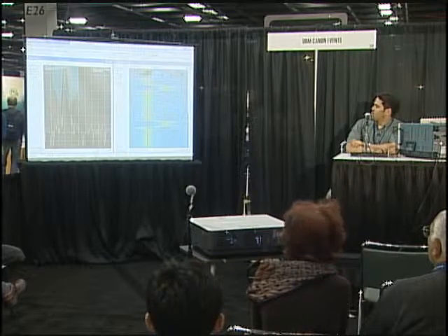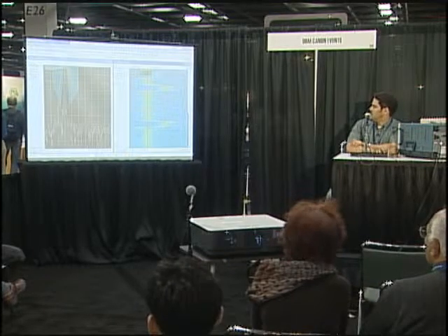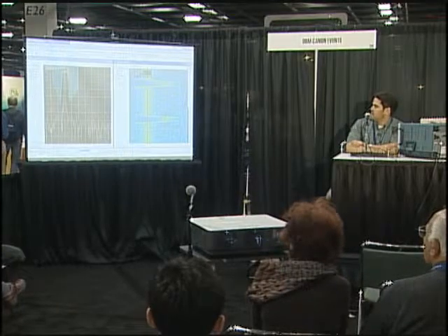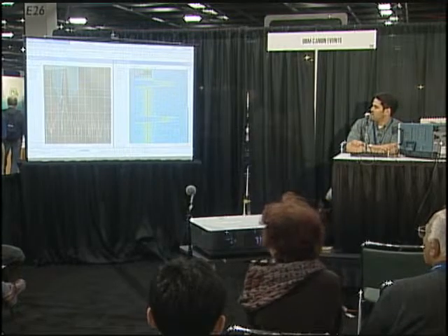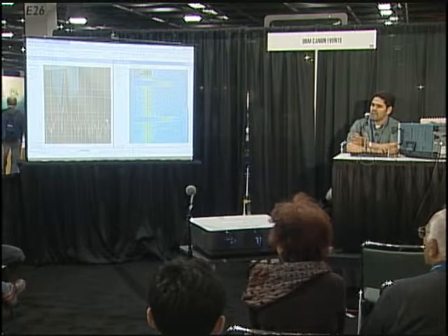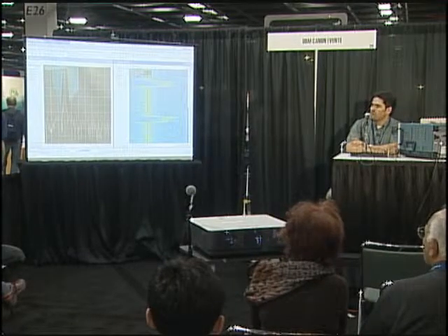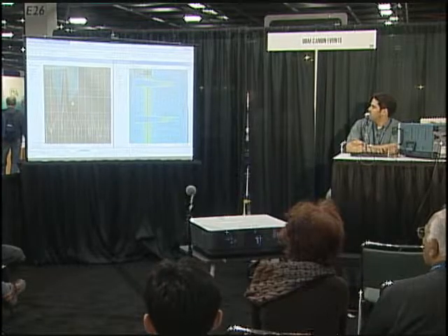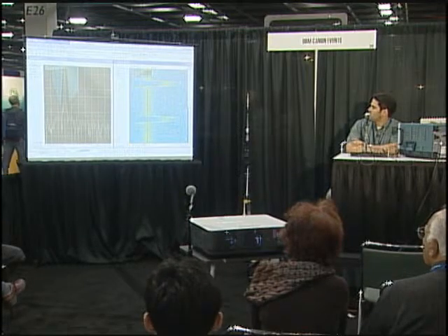Another way that we have to trigger on a signal like this is using a frequency mask trigger. And it's this mask that you see on the spectrum. And what this does is it will trigger, just like DPX did, whenever the signal hits the mask, right? So how do we create this mask? Well, there's a very simple way to do it.